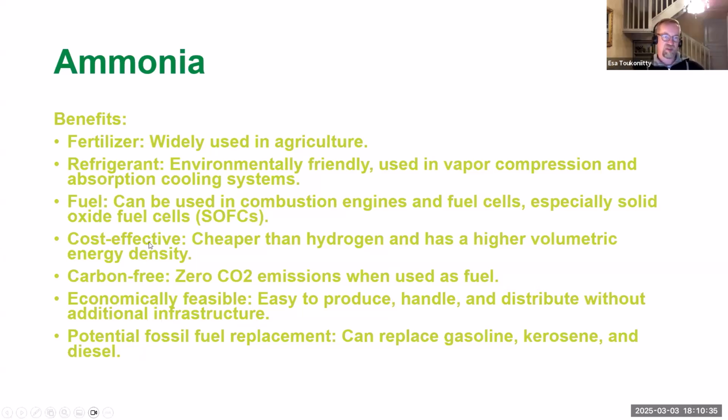According to some sources, it's cost effective, so cheaper than hydrogen, and has a higher volumetric energy density. So that comes clearly from the fact that this can be liquefied at quite low pressure. So one can store a lot of ammonia in a small volume or at lower pressure compared to, for example, hydrogen. It is a carbon-free fuel, because you don't have any carbon atoms in ammonia. If you burn it, you will not get CO2 emissions.